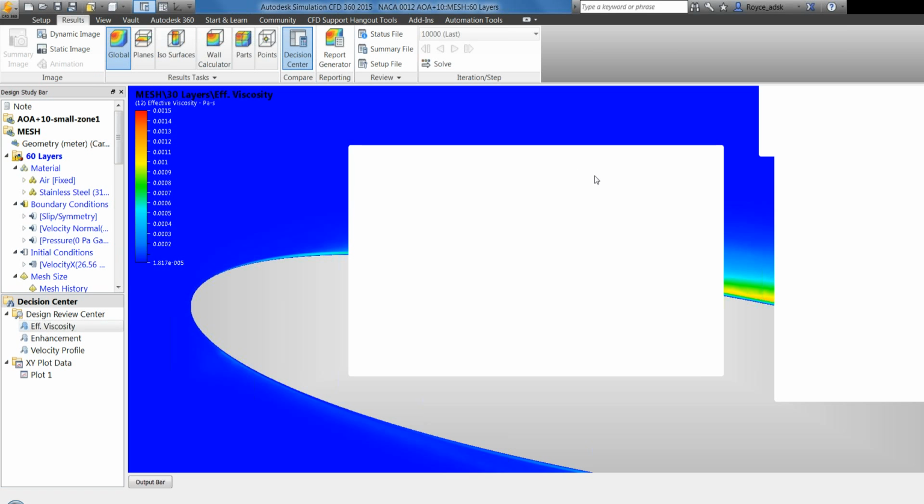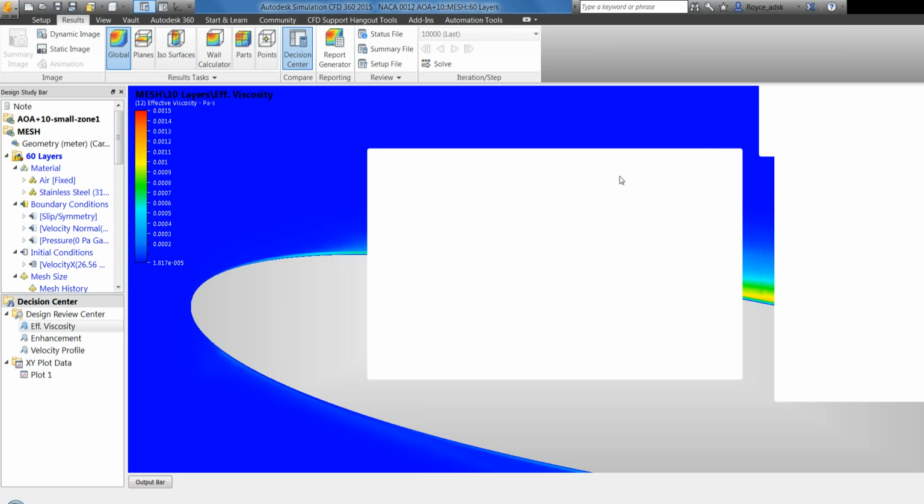So we're looking at heat exchangers. If you're not looking at pressure drop, let's say you have a defined mass flow rate on the two parts of your heat exchanger, and you're really trying to look at the heat exchanging performance from the hot and cold side, for instance, then this does apply a little bit. But since you're not looking at pressure drop, you can get away with a little less mesh because you can have less boundary layers. Maybe 5 to 10 when you're leveraging the SST, especially when you're looking at liquid-based heat exchangers. Okay, and that'll be much more accurate.